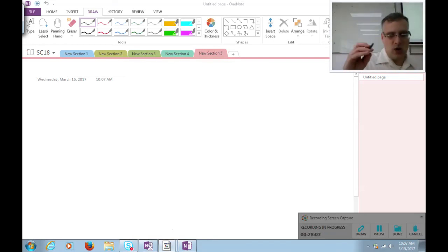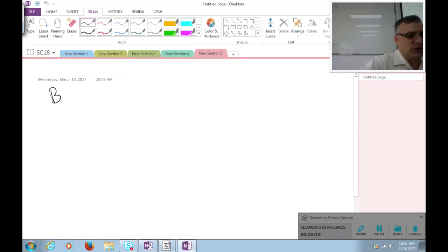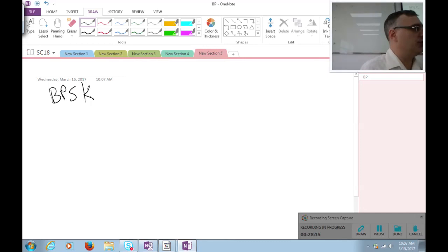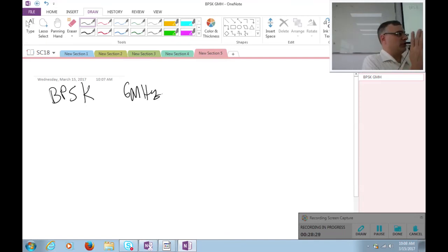And let's work through this, because it's a good exercise. If I have binary phase shift keying, basically transmitting pulses of plus and minus amplitudes, 1 bit per symbol, and I have a 6 megahertz symbol rate, and I'm using ideal sinc functions for my pulses, no roll-off factor whatsoever. So remember, the Fourier transform of a sinc pulse is a perfect box. It takes ideal hardware to do something like that. It's not realistic, but let's say for the sake of argument, what is my bit rate in a 6 megahertz channel?